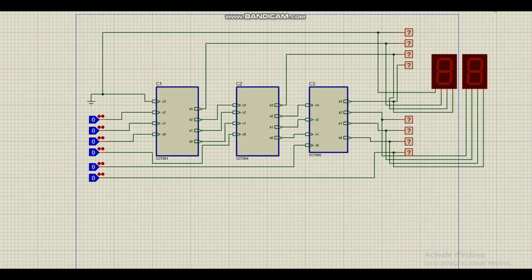Another improvement is that we took our binary output and converted it into decimal output. We did that by converting the corresponding binary into BCD output, and then we used the 7-segment display to display it. We did that with a method called shift-add-3 register, or double dabble method. In this method we shift the MSB to the left, and every time we analyze whether the number in the box is bigger than or equal to